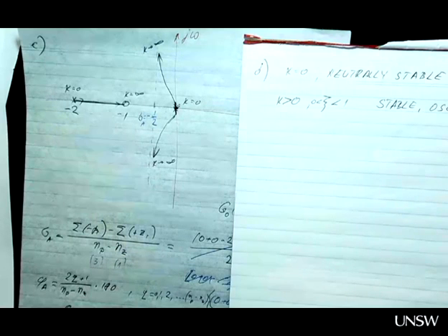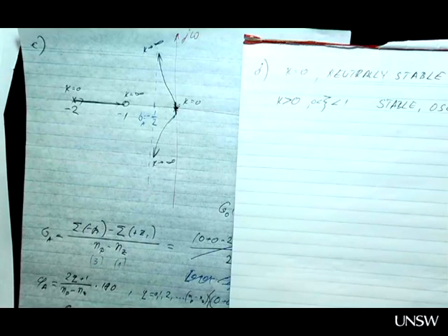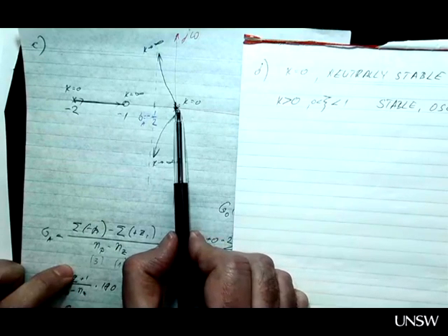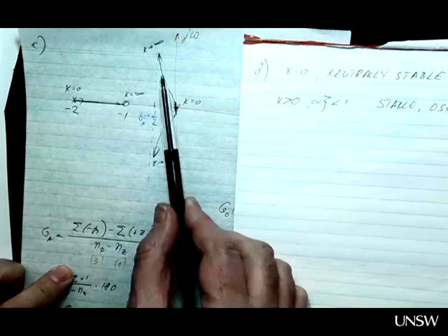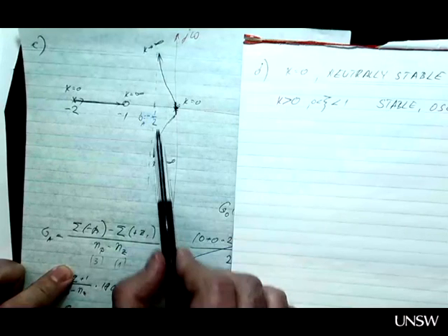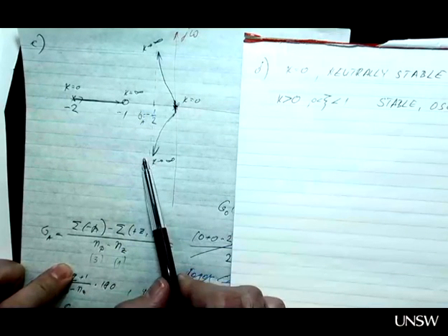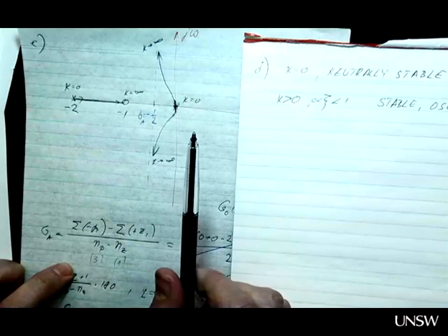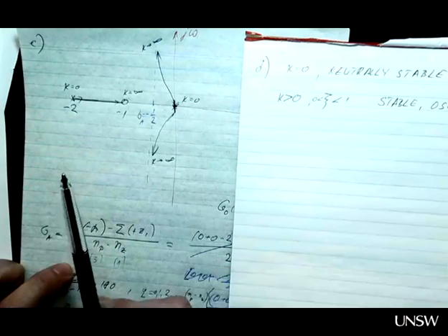So this is a case when we actually don't significantly improve the behavior of this system with a negative feedback loop. No matter what value of K, we will stabilize the system, move away from the imaginary axis, but the cost is that we have oscillatory behavior. So we'll never have a non-oscillatory behavior of this system, unless K is 0.